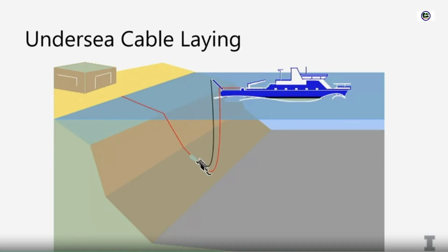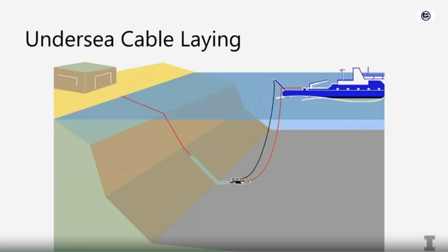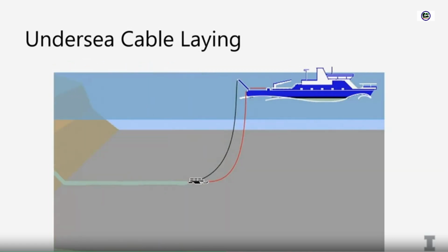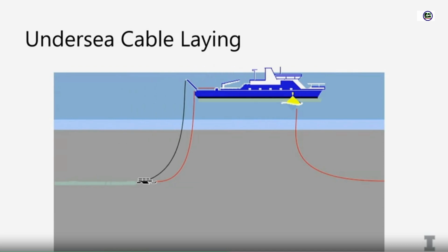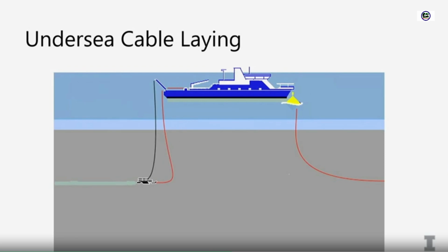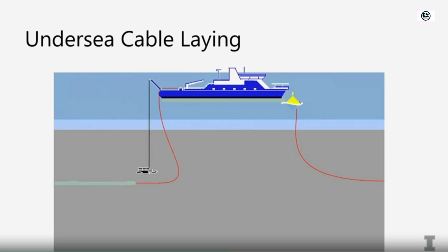So it's going to push the cable down, it's going to dig a trench, it's going to run out until it gets out to a certain distance offshore where you're not doing fishing anymore. Because people don't fish in the middle of the ocean. The fish like to live near shore because that's where their food is. And so at some point you don't need to bury it anymore, and then you're just going to spool it out. So that's what we're doing here.